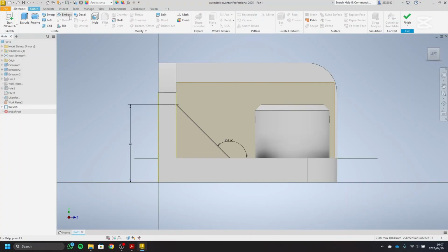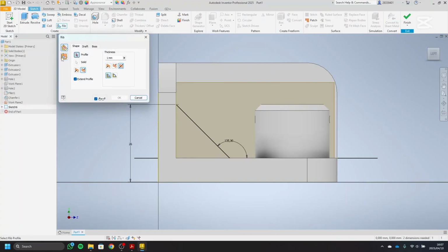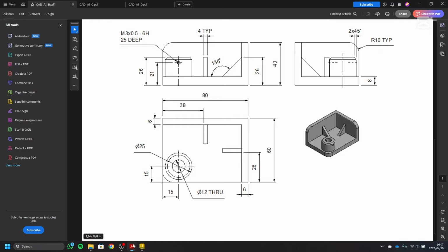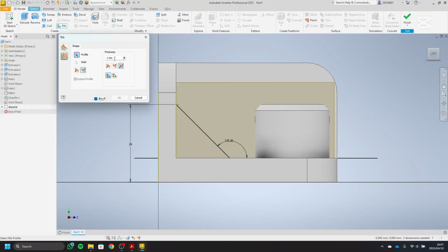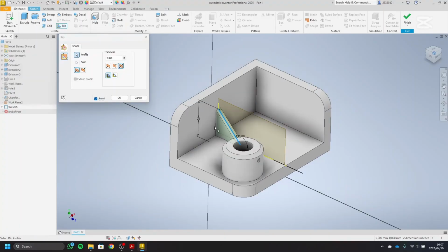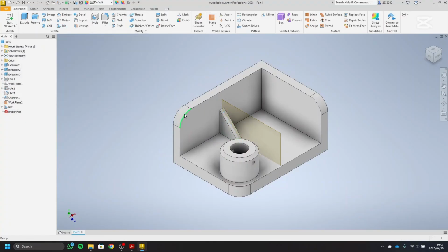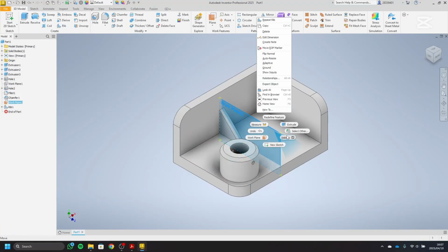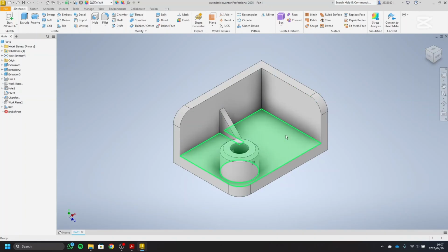So we can extrude this to the normal rib maneuver. It's a thickness of 4 millimeters. So just put in 4, and profile would be here. And if we have a look from this side, there's the rib created. Okay, and then you can just remove the visibility of this plane. So we can do the same thing approaching from this side.